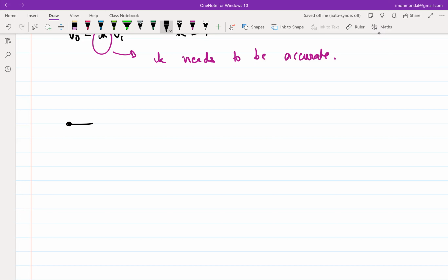You don't want to undershoot, because you want to have a good experience. You don't want to overshoot because, obviously, traffic lights. So let's say you want to achieve a goal of 40 kilometers per hour. This is my desired speed. With anything in negative feedback, there is an actual output and a desired output, and you try to minimize the difference between the desired and the actual. So this is the desired speed, and you have an actual speed, let's call it S out.